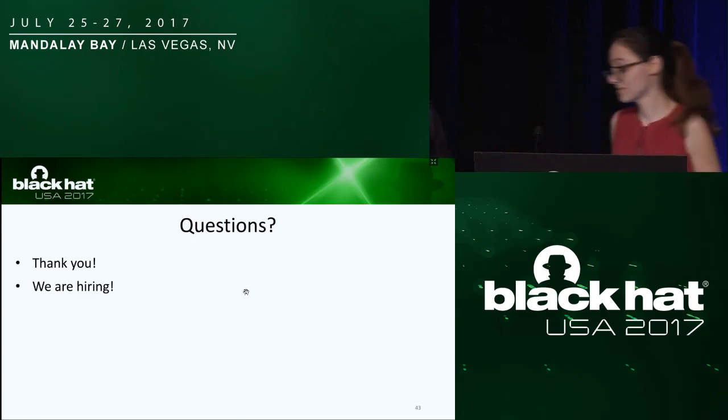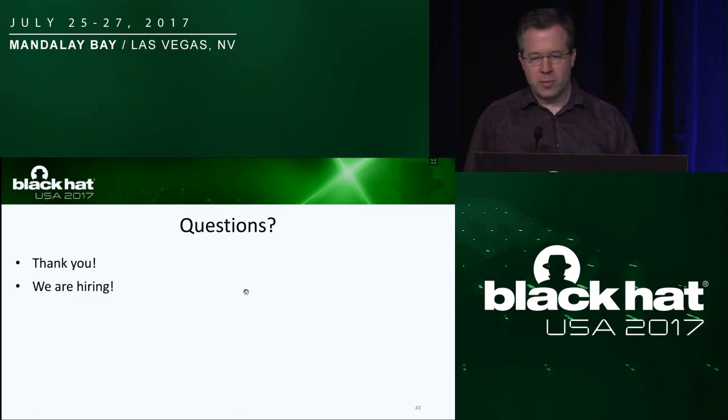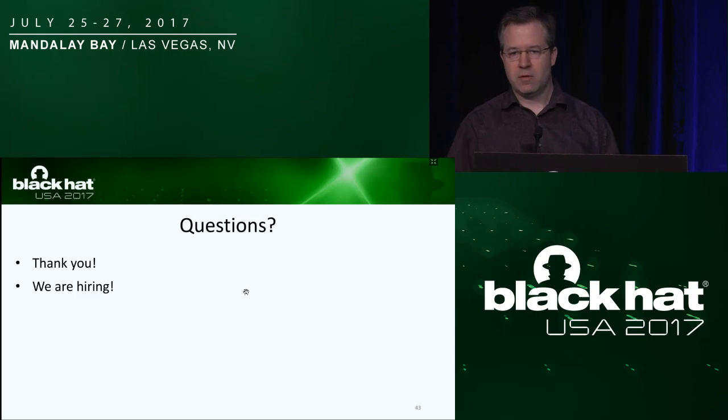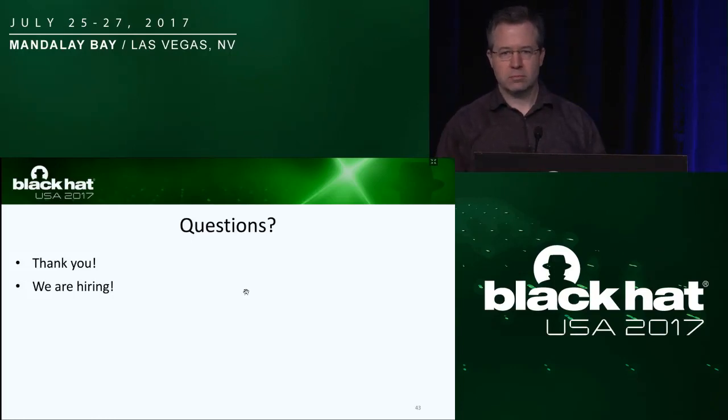I can speak to that. I think in terms of reading the memory, especially if you're talking about a system that's been compromised, like in a data center where somebody has full-time physical access to the thing, there's currently a variety of off-the-shelf memory interposers and taps that have isolation resistance that allow you to sniff the bus readily. Those are products you can essentially buy for that. What's novel here is being able to modify the contents undetected by the system. None of those interposers allow you to actually inject data into it. Did that answer your question?